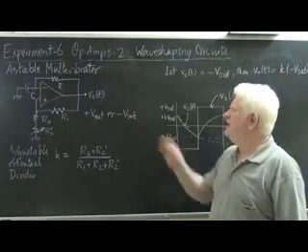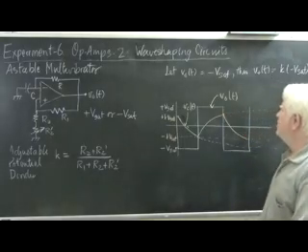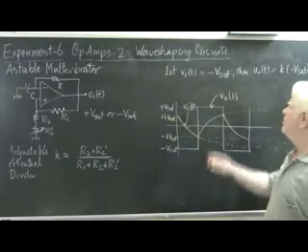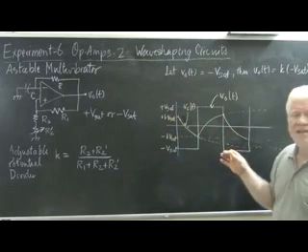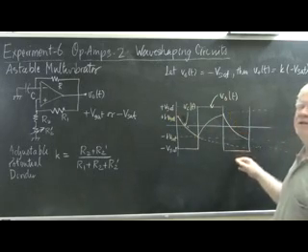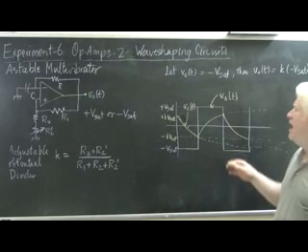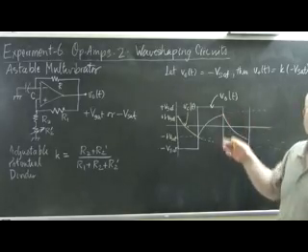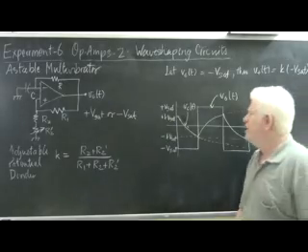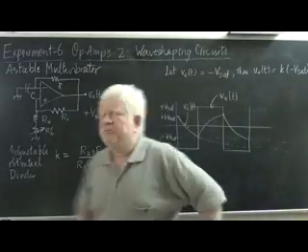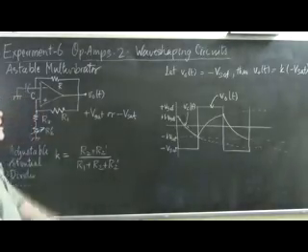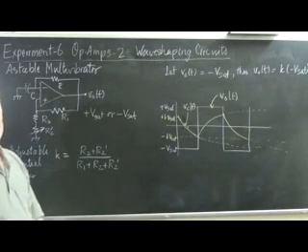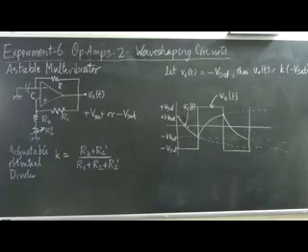This is the Astable multivibrator. So the things to observe here are that there is no input signal. All you have is a square wave output which levels at plus Vsat and minus Vsat of the op amp, and an interesting capacitor voltage that causes the op amp to behave in this manner. So you do the experiment by connecting up the circuit and observing the capacitor voltage as well as the op amp output voltage on the oscilloscope on the two channels.